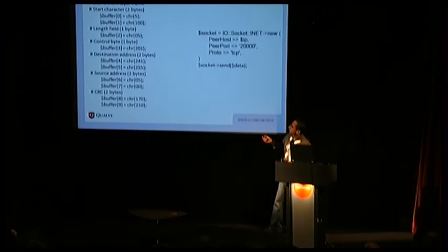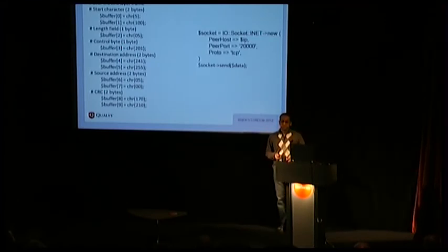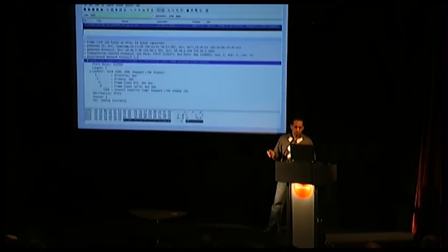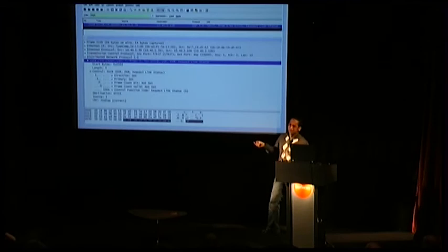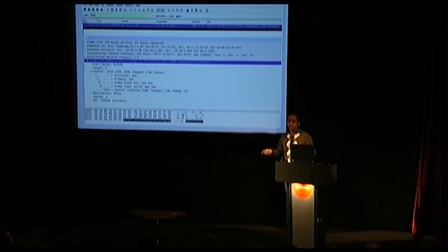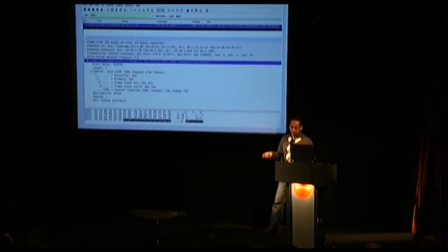So you basically, again, create a DNP3 packet, put the destination address, source address. Now you are actually calculating a CRC here. Here I've just hard-coded the CRC because I know what the packet is. And you send it away to the DNP3 server. This is the request that you see. Again, in this case, Wireshark, Ethereal, most of the packet sniffers already knew how to decipher this protocol.